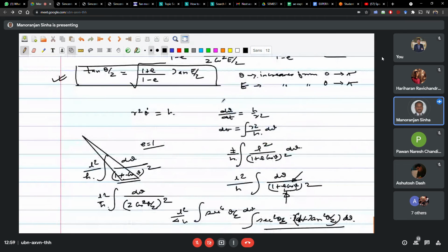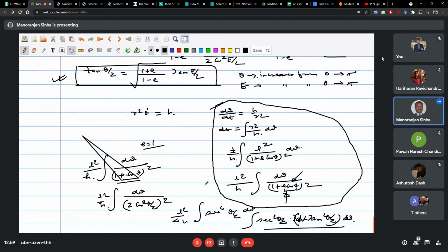What we are solving here is to get the future position of the satellite. The future position is found because a, e, i, small omega, capital omega are all constants. Only theta is changing. So instead of directly estimating theta, if we can estimate E, then our job will be done. Later on you will see that M equals n times (t minus tau). This quantity is equal to E minus e sin E, where M is the mean anomaly and n is the mean angular velocity, as in the case of the ellipse we have looked at.